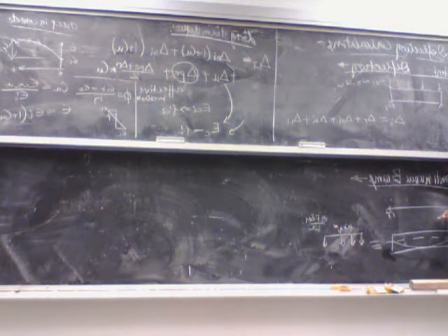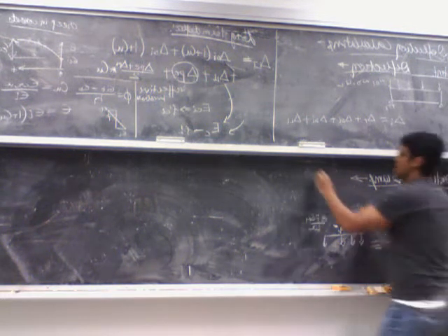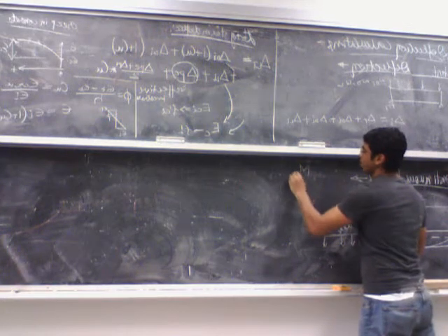In this case, if I replace this pre-stressing force and the eccentricity with its equivalent load and apply it on this indeterminate beam, the moment diagram that you get is not the same as minus F times e naught. That is due to the fact that you have some secondary moments M2.